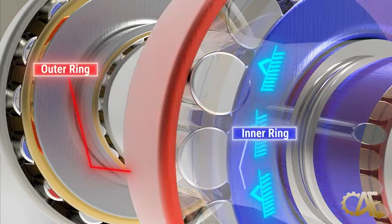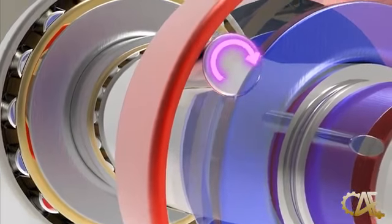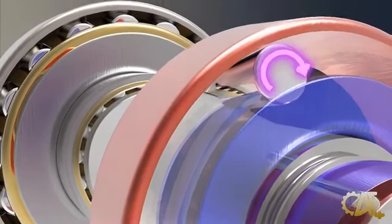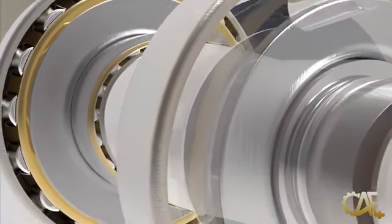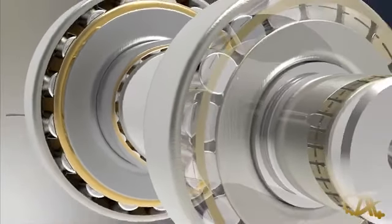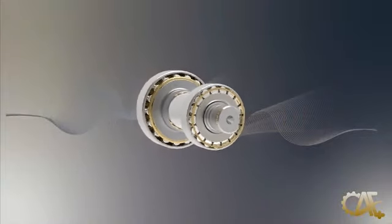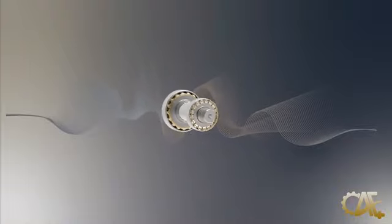As the outer ring begins to rotate clockwise, it imparts a tangential velocity to the roller. This means that the surface of the roller in contact with the outer ring receives a certain speed in the opposite direction. This is due to the friction between the roller and the outer ring surface. Since the inner ring is stationary, one side of the roller remains in contact with it, both preventing any rotational motion and initiating the roller's roll along the interface between the outer and inner rings. This innovative design allowed for smoother motion and significantly lower friction, making it ideal for high-speed and heavy-duty applications.